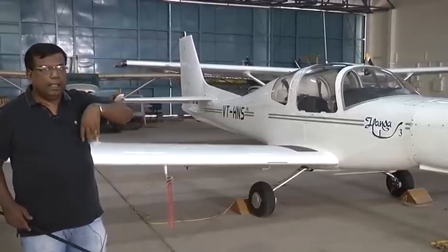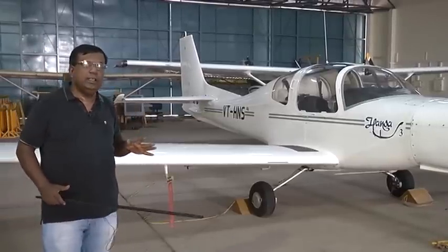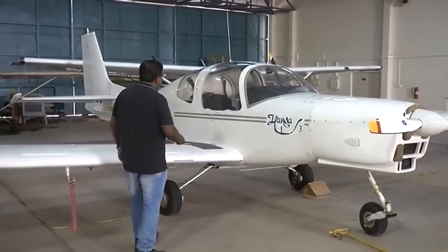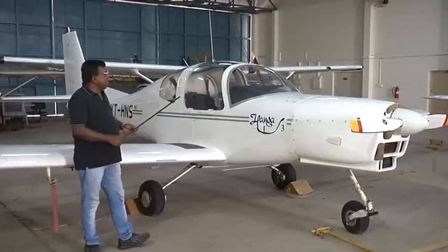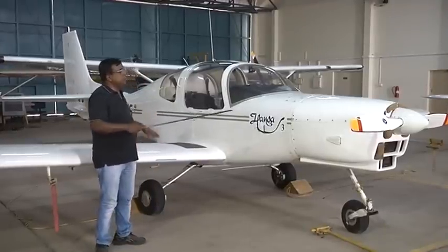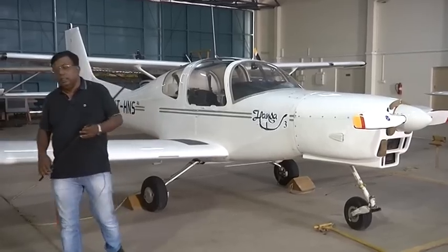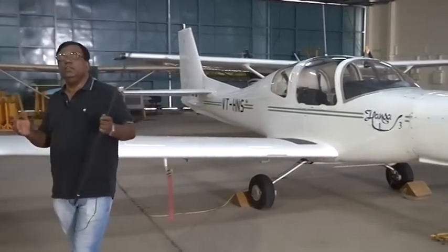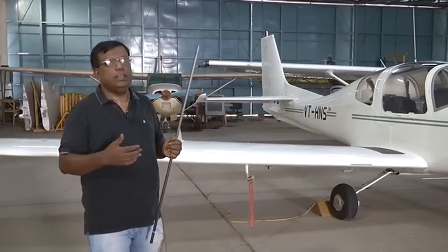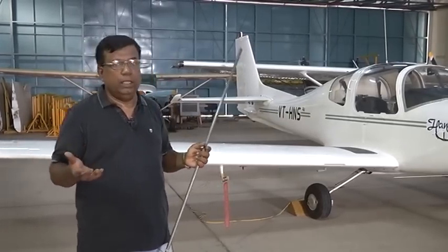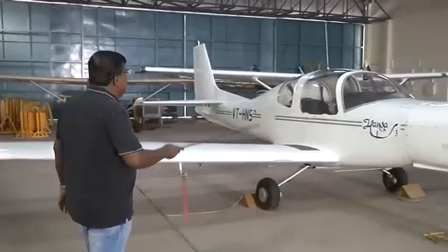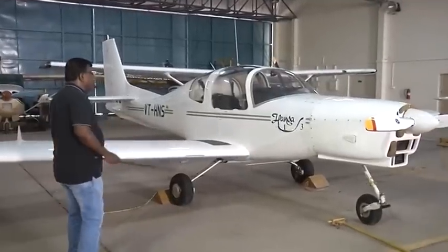So now, when I am analyzing the cruise, I am very clear that the whole mass of the aircraft is at the center of gravity, and the net force I have calculated by transferring them from different components. Then I am resolving those forces and finding accelerations, and if it is a non-accelerated or unaccelerated flight, I am putting that 0 and going step by step whatever is required, right? So that is what is typically the point mass model.